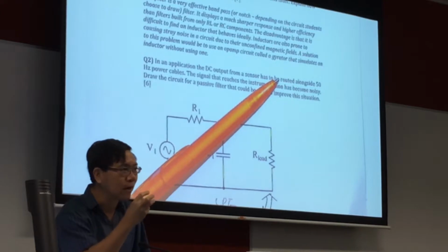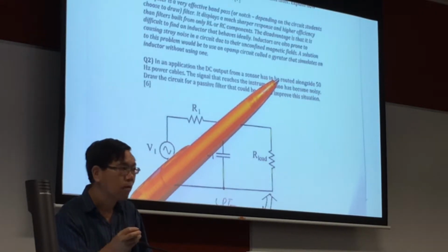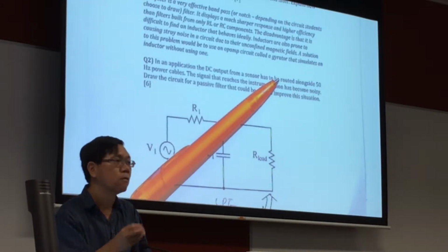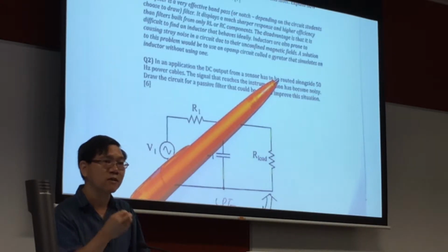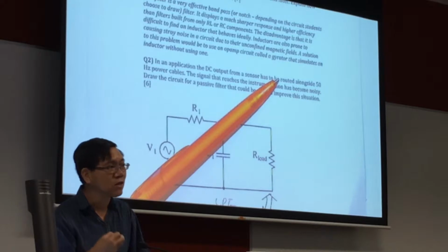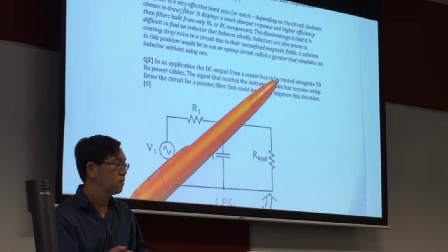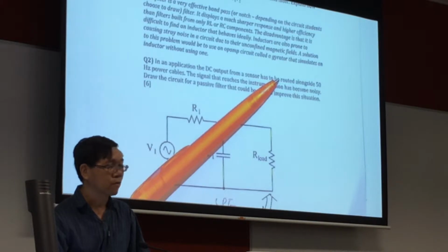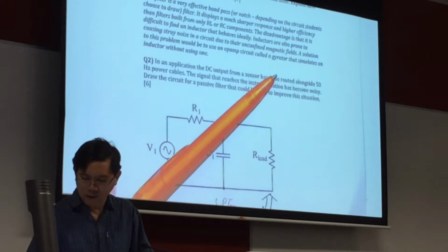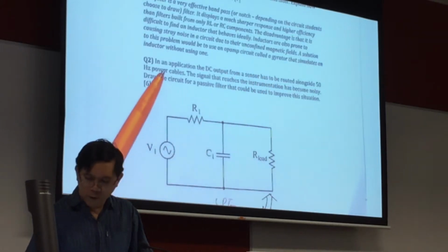Towards the end of chapter 8, lecture 8, the gyrator. But what's the disadvantage of the gyrator? The disadvantage of the gyrator is, on the other hand, one end must always tie to ground. Okay? So some circuits may not be able to be implemented. That's in that sense. Is it okay, class?